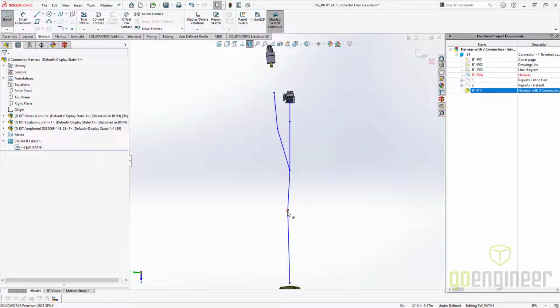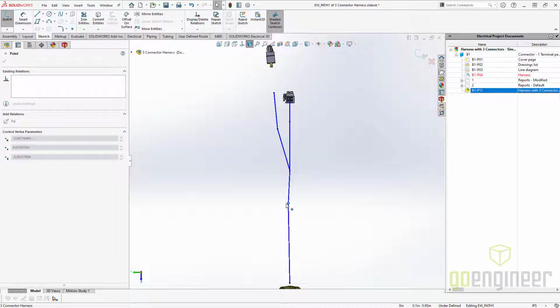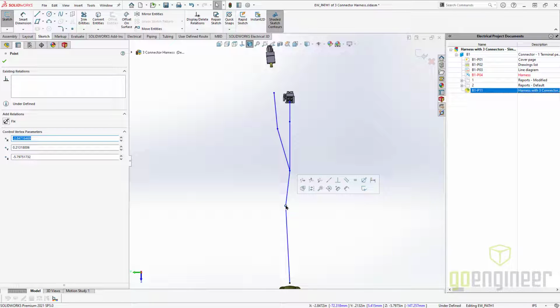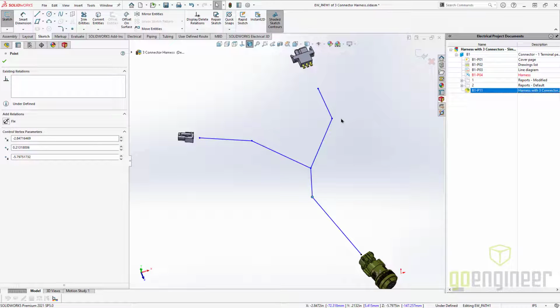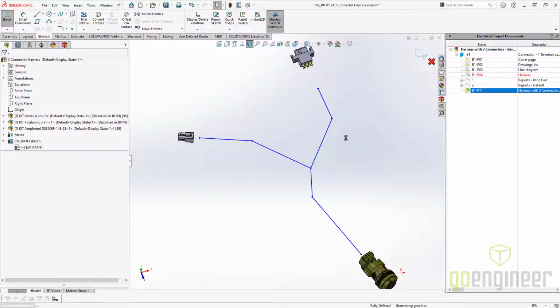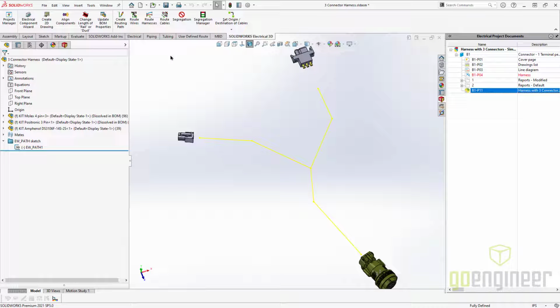The reason I do that is when you move it and you're only looking at a standard orientation, it's only going to move two dimensions. It's not going to move in 3. If you're in an isometric view, it's very easy for it to get all 3 points oriented differently there. So I also will fix a point once I get it to a spot where I like it. I'll fix it into space so it doesn't move again. But all right, so that's the 3D sketch there. That one was using the create route path, so it names it correctly for you. It also changes the color, but again, it's just a 3D sketch with that specific name there.